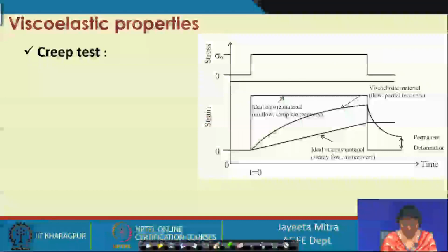Here what we do is apply a constant stress, and maybe this is a significant amount of higher stress, not very low in magnitude. We apply that, and with time we observe what will be the strain in the material. We observe the strain, or the response of the material to the stress. So, this behavior will be observed.